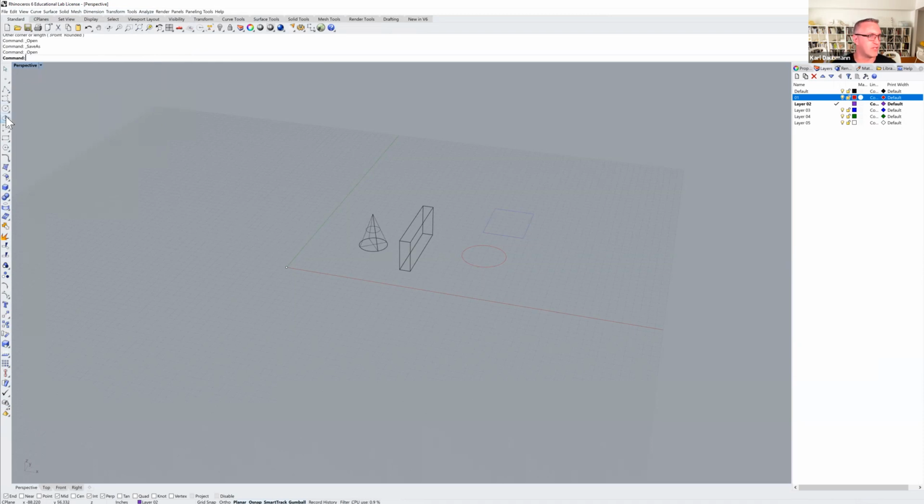And if you're not familiar with them, if you mouse over them, it'll tell you what they are. I tend not to use the icons when I'm modeling, because I can be a lot faster with other things, right? So if I type L and the space bar, now I can draw a polyline, right? And for me, it tends to be a little bit slower going and finding these in any icon on the left.